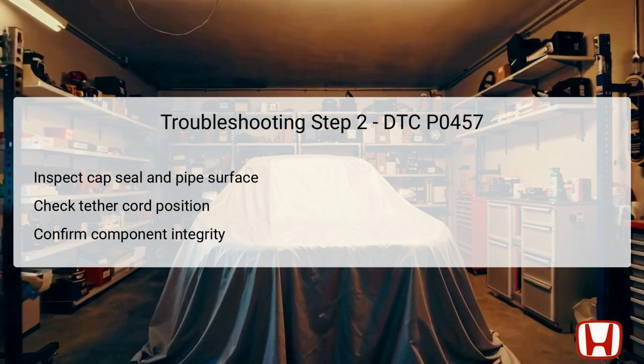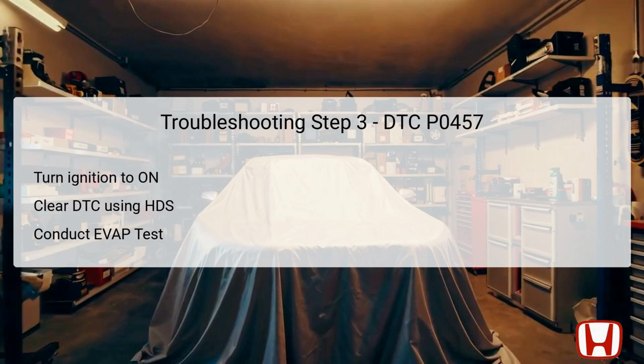Completing this step thoroughly allows the technician to gather valuable information on the state of the EVAP system, especially concerning each critical component's functionality. The third step involves verifying if any issues persist by utilizing the Honda Diagnostic System, HDS. Begin by turning the ignition switch to the on position, which activates key electrical systems in the vehicle, including the powertrain control module, PCM. The next action is to clear the P0457 DTC using the HDS, effectively resetting the system's